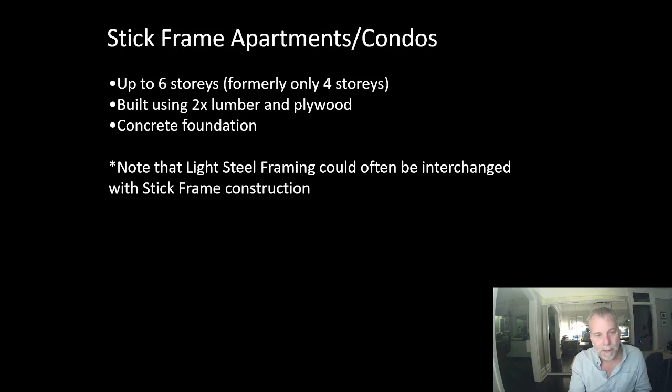Stick frame typically have concrete foundations. There are other foundation systems. We might use block if we don't have a basement. We might use preserved wood. Preserved wood is allowable under the building code, but hasn't really gained traction. I don't think people have confidence in the longevity of a preserved wood foundation yet.